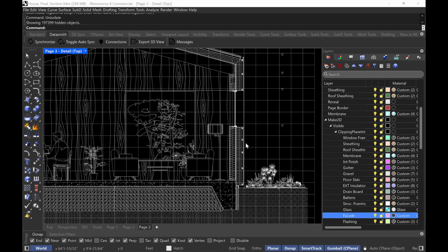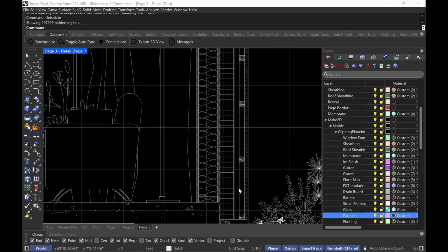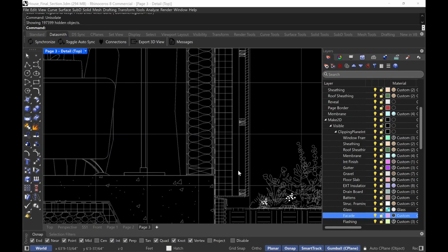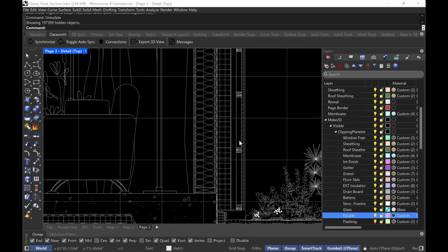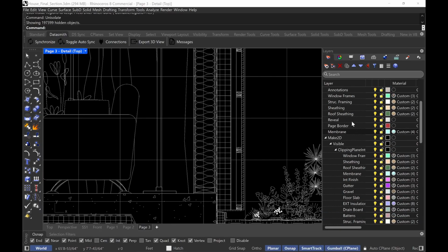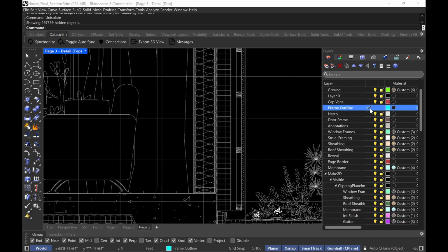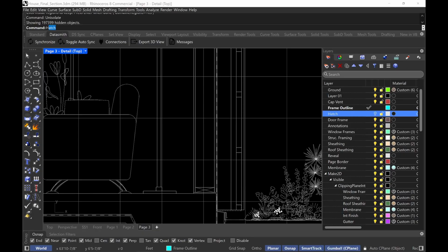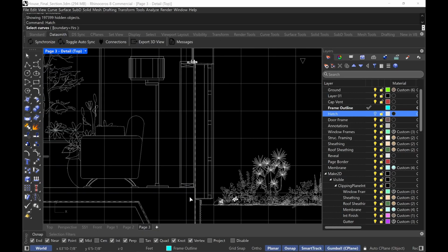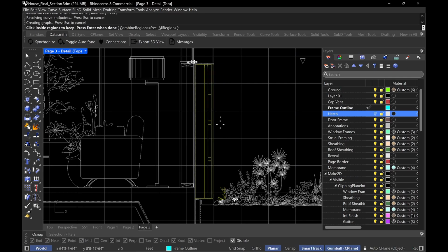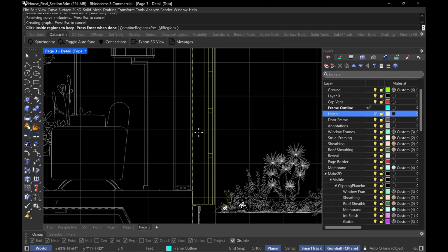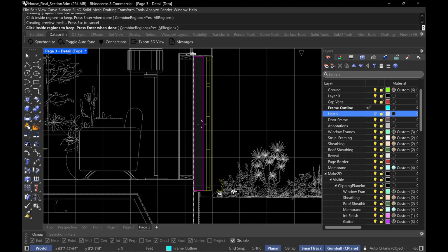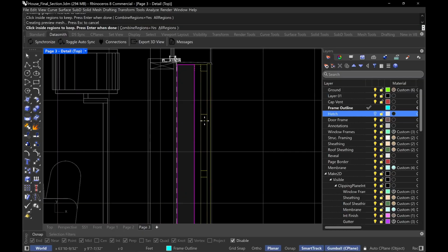So I'll give you a good example. Let's say you want to hatch this cavity here, right? You can either just draw a rectangle around it and then hatch it like that, or let me turn off this hatch. Let me make this active real fast, right? So I can do hatch, boundary, I could select all of these as a boundary, for example. Enter. And like for this cavity, for example, you can click right there, you see? Or maybe this cavity right here. You could do it that method as well.